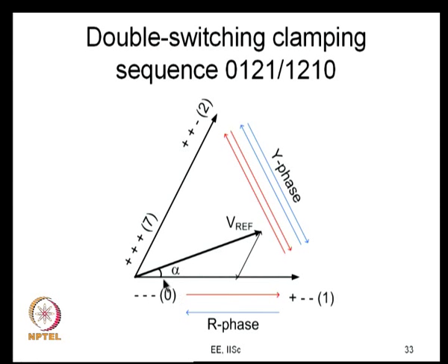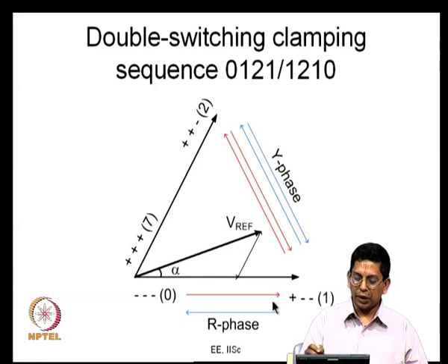Right now, we have moved off. We are now not looking at the inverter as 3 different phases, or 3 independent phases. We are looking at the inverter state, and that is why we are able to say this. We are asking the question: why should I apply this active state continuously for t1 seconds? Why not apply it later? Why not apply it once more?